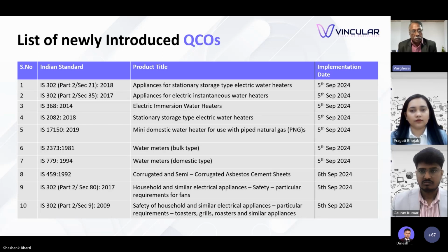If a product is subjected to abnormal operation like higher voltage, or operated without water, or operated under abnormal conditions, there is no problem if after the operation the equipment does not work; the standard says no problem. But if it is tested for leakage or shock after it is operated under abnormal conditions, it definitely should not give a shock. So even when it is failing, it should fail safe. The fail safe principle is integrated in almost all of these standards.